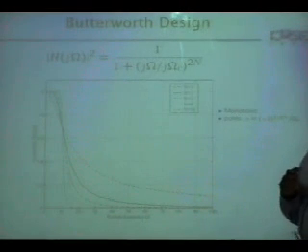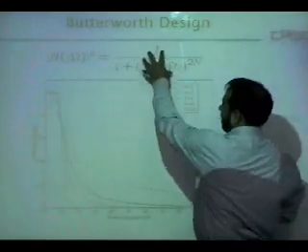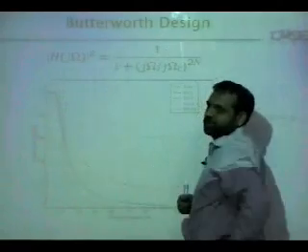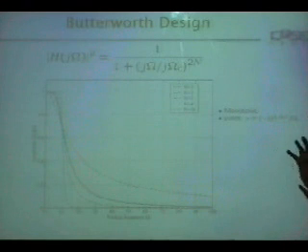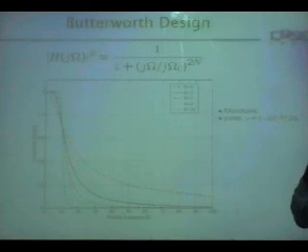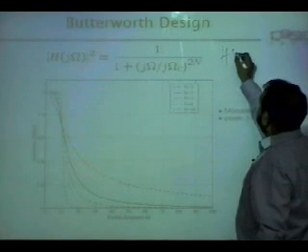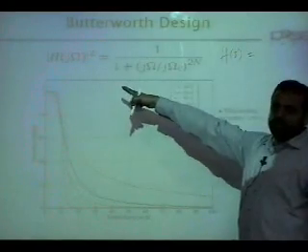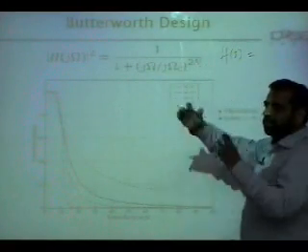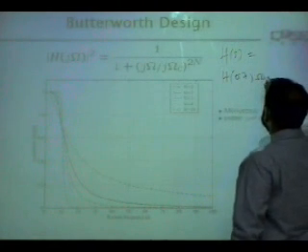So if somehow I can design something in electronics which results in this, it means I can implement this filter, right? And this is analog electronics: if I can come up with a combination of capacitors and resistors, from my perspective an H of S. Filter design means you need to come up with an H of S, and the relationship between H of S and H of j omega is, as we know from the relationship between the Z transform and the Fourier transform, that s is sigma plus j omega.